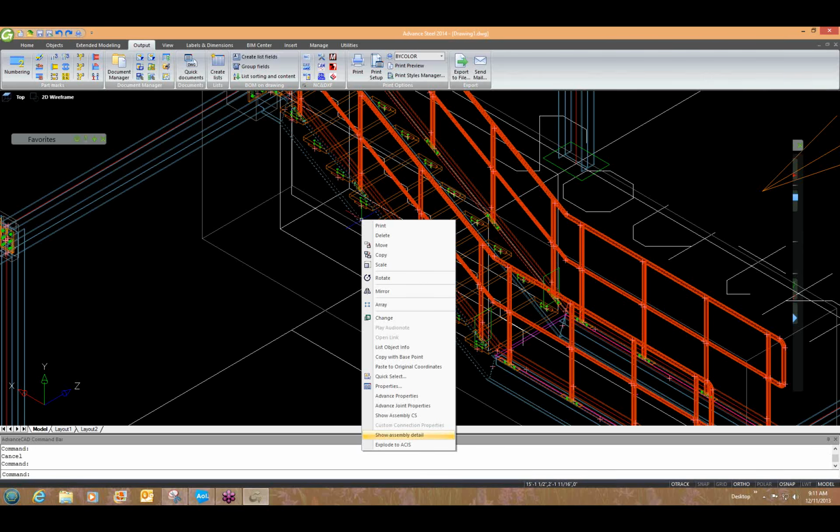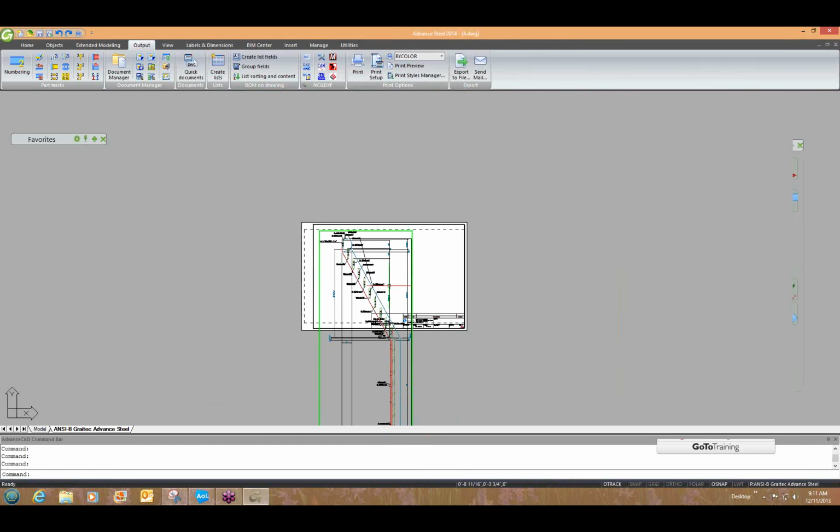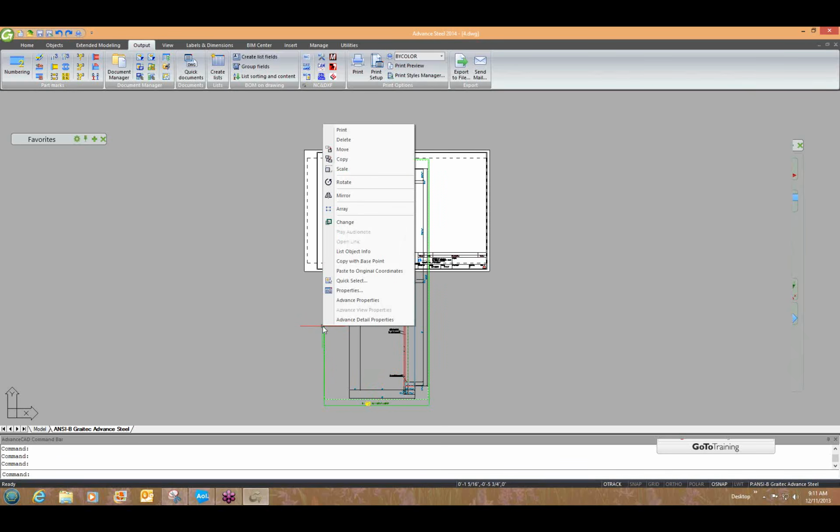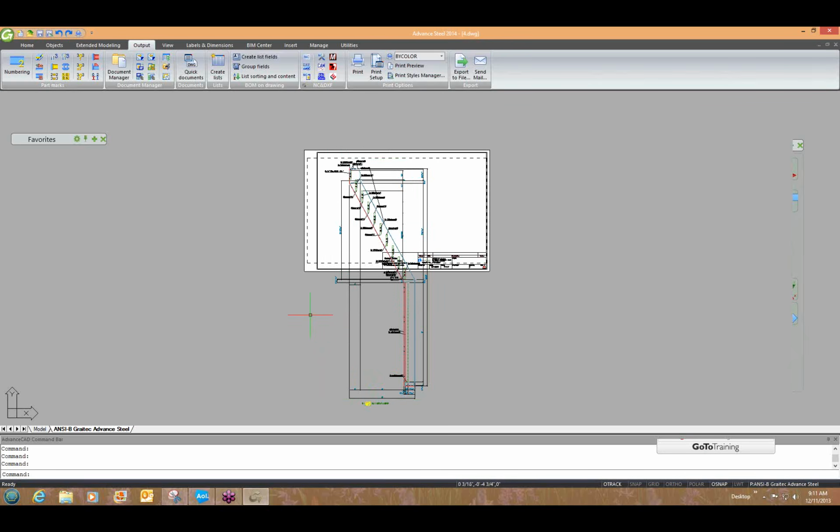It has been already detailed. Here it is. Here it's your stairs. And you know why it is upside down? Because your UCS wasn't right. Your Y axis wasn't up. Your Y should be up, like the UCS on the bottom left on your screen. The UCS on your model should be like this. Seems to be good, Chuck?